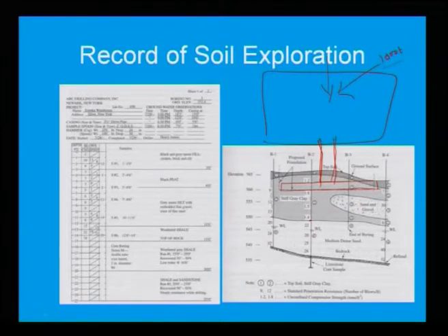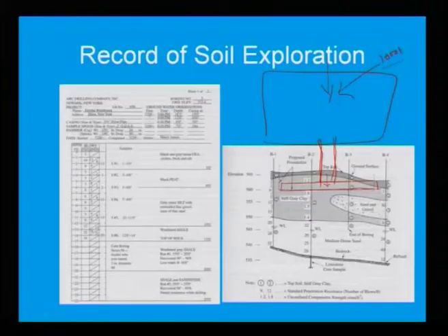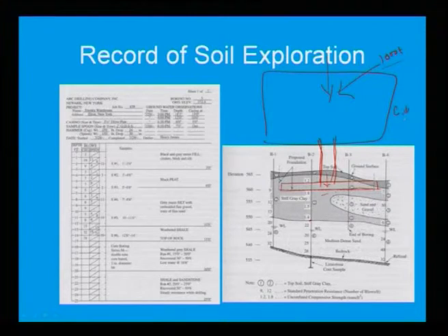So, definitely how will this building resist? This load will be transferred from superstructure to substructure, then to foundation, and the foundation will be acted on by 1000 ton. If the foundation takes the 1000 ton load, who will take this load? Obviously, it will be taken by the soil, by means of the strength parameters, your C and phi. If your C and phi values are not large enough, then it is not going to take it. So, what will happen? The building will collapse. That is why these boreholes have to be cross checked with each other.